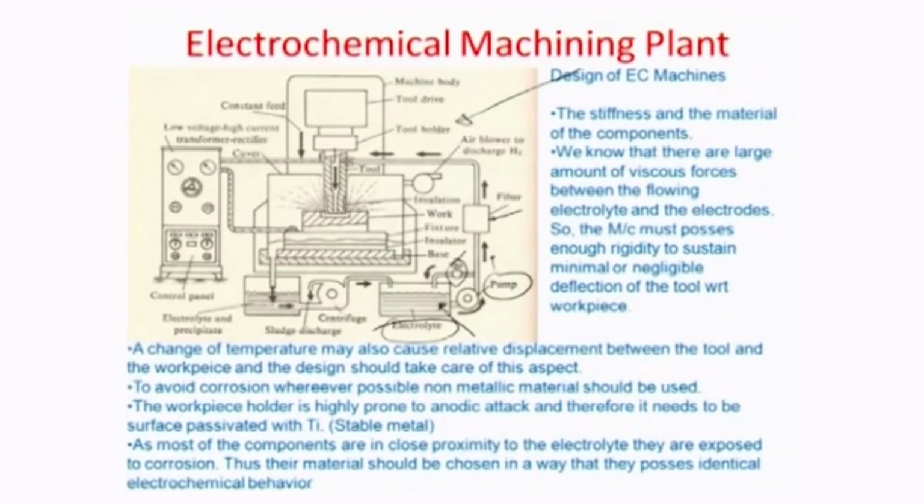into the tool. This is a coaxial tool where you can see the electrolyte coming out of the tool in a very small slot at the end of the tool here, right here, and then the electrolyte flows in both directions, okay, over the workpiece surface. As such, it discharges whatever hydrogen or gases emanate from the tool side. There should be a capability of blowing them out.